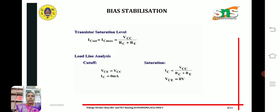Next we are going to calculate the load line analysis. For this we consider the transistor saturation level, where we get the maximum collector current, which is equal to VCC divided by RC plus RE. For load line analysis we consider the cutoff values. Here the collector current is taken as IC equal to 0 milliamps and VC equal to VCC. For saturation, VC equal to 0 volts and IC equal to VCC divided by RC plus RE.